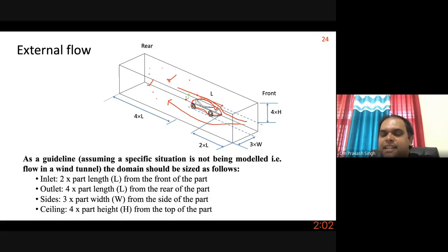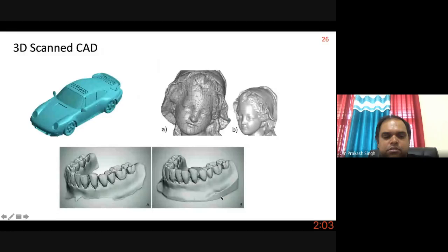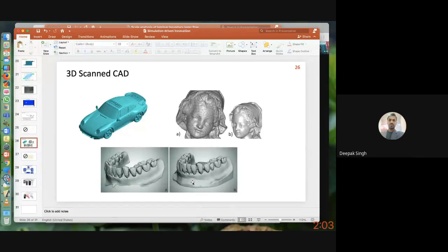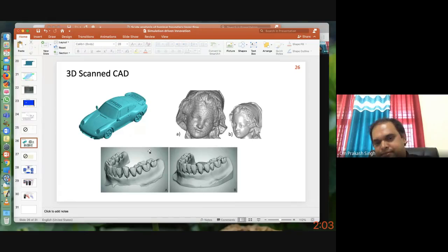It has to be watertight, so there will be no leakage inside the model. You can have a conjugate heat transfer where you will have two volumes, one volume for the solid, one volume for the fluid. This is how the algorithm of volume meshing works. I can show you one. If there is a leakage, it will not leakage in a sense. If there is any hole or error in the surface, you cannot create the volume.